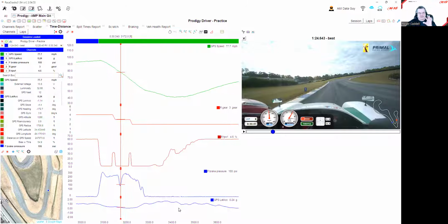I want to point out something you can see with your eyes that is not the perfect way of providing braking for the cars going into the corners. This should come up, it should have a bit of a plateau, nice and flat, and then it should have a nice trail to nothing and no huge drop off right at the end when you're turning in. Because remember, you're working the weight, you're working the chassis.